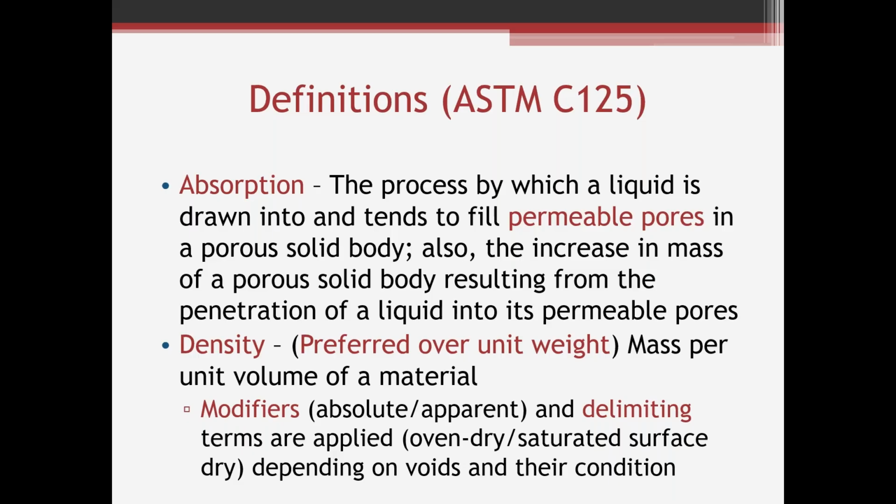It's really just mass per unit volume, pounds per cubic foot, grams per cubic centimeter, something like that. A lot of times you might see some modifiers used with density that give you a little more information on how that density was calculated, or what's included in that density: oven dry density, saturated surface dry density, things like that.